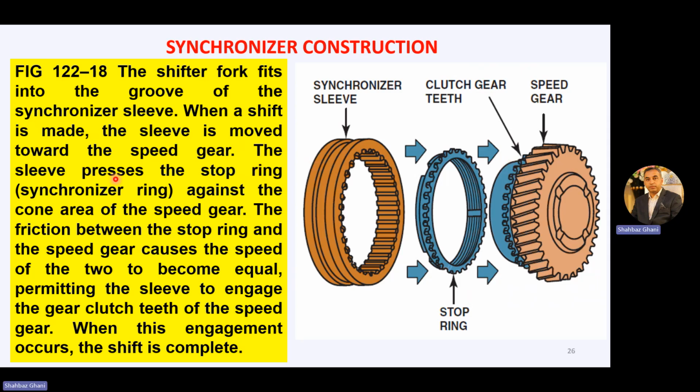The sleeve presses the stop ring against the cone area of the speed gear. This is the cone area of the speed gear.